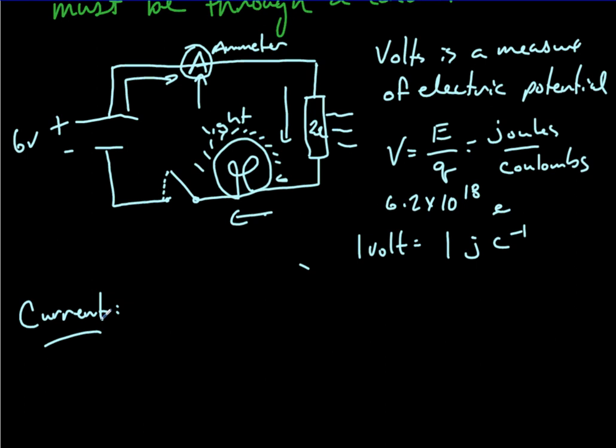Right, right. So the question is, does an ammeter affect the circuit? And the answer is yes. An ammeter, even though it's meant to have very, very low resistance, has some. Even the wires themselves, although we consider them to have no resistance, have some, and so would an ammeter. It's like that old saying, to test something in science you have to affect it in some way, so to know its true state is very difficult.